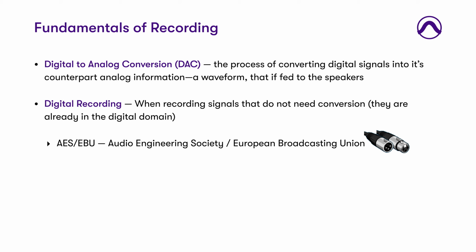The connector for this standard is actually an XLR, so it looks exactly like a microphone cable, but the signal that is transferred on it is digital, not analog. The second is a more consumer standard, and while it is still used in studios, it isn't as preferred as the AES connection. SPDIF, or Sony Philips Digital Interface, uses the RCA connectors to transfer signals from one digital device to another. It is quite commonly used with home theater equipment too.